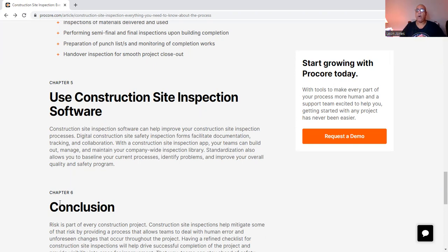You also have to take quality control tests like slump, air. When you're out there doing asphalt, the contractor is going to take cores. They're going to be tested. You're going to have to do gradation for aggregate. Aggregate could be number 8 stone. It could be number 53 stone. Has to pass through sieves. You're also going to use an LWD. Indiana uses an LWD. Some use a nuclear density gauge.